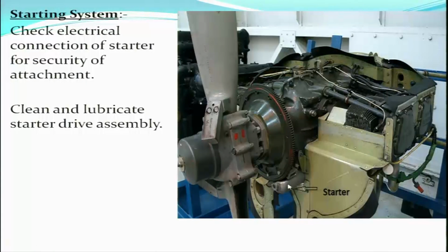Here in the figure you can see this is your starter. Check electrical connections of starter for security of attachment. First of all, we will check whether the starter is securely attached. Then we check the electrical connections in the starter are in place, whether they are properly connected.